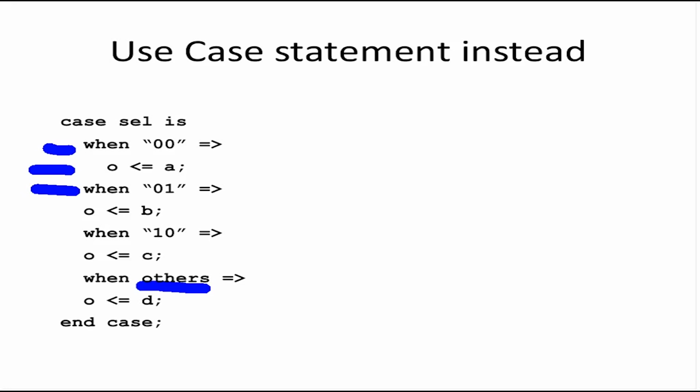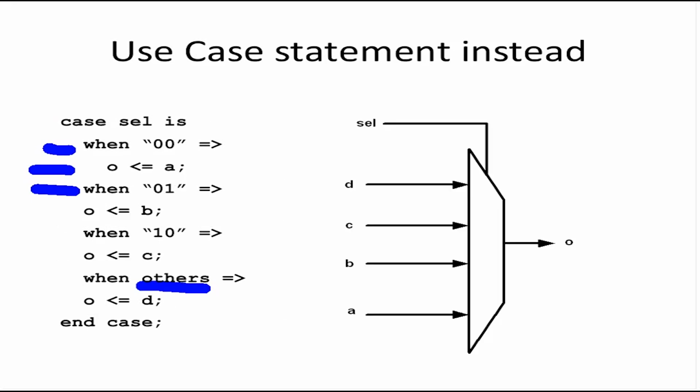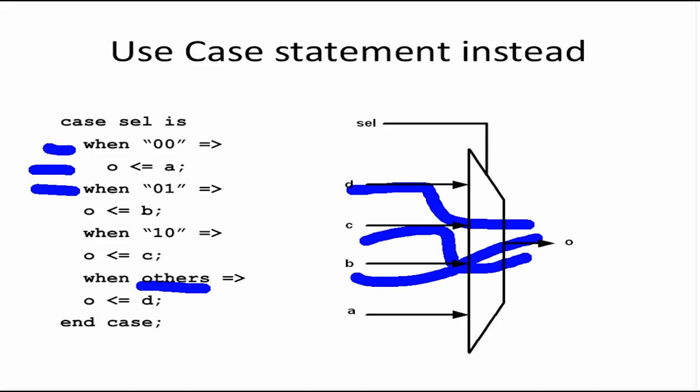This kind of code results in a proper mux structure where every input has a similar delay to the output. Again, the standard cell library might not have a 16:1 mux, but it will have some kind of mux. Seeing the case statement, Design Compiler knows that you want a balanced circuit, and it will try to use whatever mux designs are available to implement it.